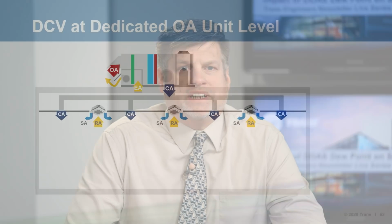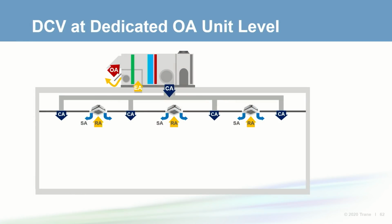Next, let's move on to demand control ventilation. In a dedicated outdoor air system, DCV can be implemented at the unit level or at the zone level. Unit level DCV has limited use. It can only be used effectively when the dedicated outdoor air unit serves one ventilation zone. This might be the case in a large open office area. There may be multiple terminal units and temperature control zones, but ventilation air is distributed throughout the area.